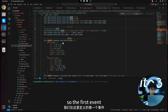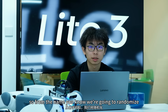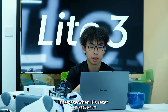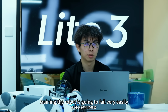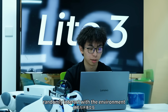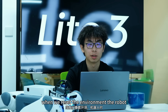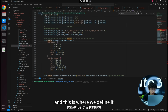So the first event we define here is randomize reset base. From the name, you know we're going to randomize the base when it is reset. Sometimes at the very start of the training, the robot is going to fail very easily, since you just randomly interact with the environment. When we reset the environment, we're going to change the position, rotation, and velocity of the base. And this is where we define it.